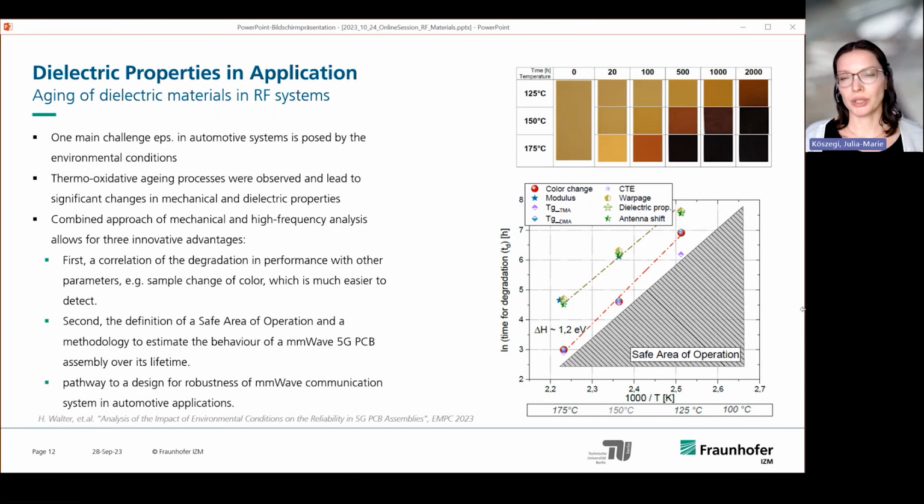If you know that your decay, for example, will increase a bit with time in your direct application, you know that your resonance frequency will shift. So you can design it in a way that it will be operational for as long as possible. It actually can first get better and then get worse. So this is another aspect, especially in combination with the reliability aspects that we are investigating here in-house.